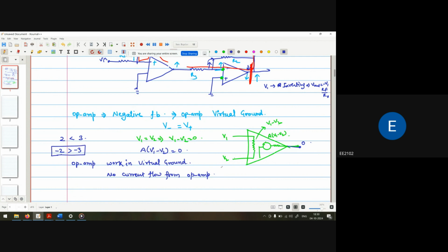So if this value increases and I multiply it with the minus sign, it becomes a decreasing value. Now I apply a small signal change in the positive direction, and I get it reverted back in the loop in the negative direction. So I can say this is a 180-degree phase shift, and a 180-degree phase shift means negative feedback.